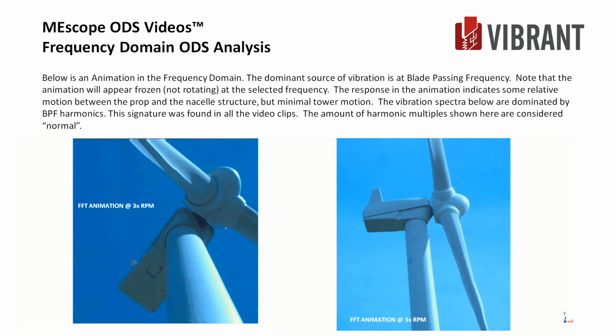So this is blade pass frequency, and I believe there's probably some misalignment issue between the main drive shaft and the prop on the end. And it's a good view here that you can see it's kind of a pitching motion, and it looks like an alignment issue. But we'll have to wait and see what the wind farm says and how these units react to that vibration over time.